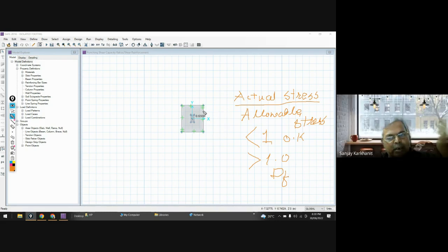Now let us see what this 0.65 means. You are having 35%. So 0.35 is your factor of safety, because anything less than or equal to 1 is okay. So even if this comes out to be 0.9, then as per our calculation or theoretical concept, we'll say that it is okay, but it is just very near. So I will say try to create this something around 0.8, or 0.75 to 0.85.